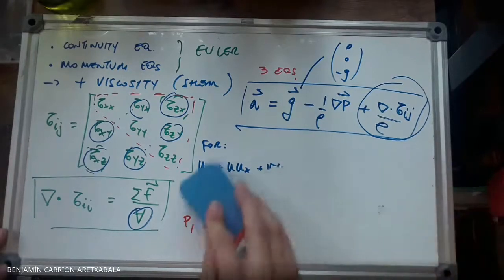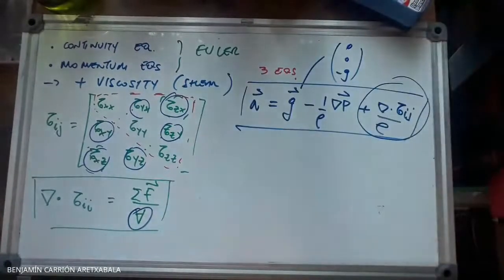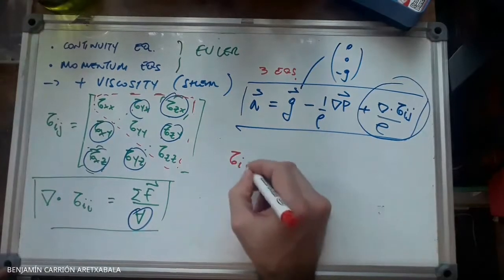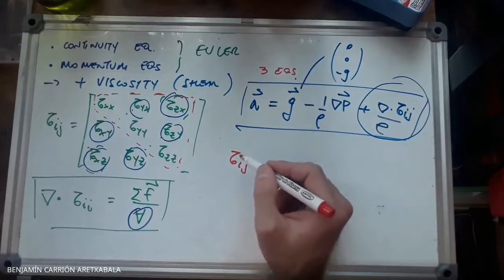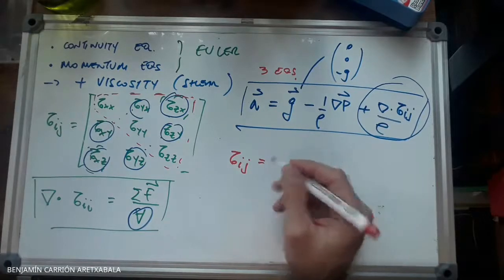Okay, let me try to make myself clearer. We know these are fluids, so we know these are flows. So we're going to relate the shear stress acting on the i plane in the j direction with the properties of the flow.